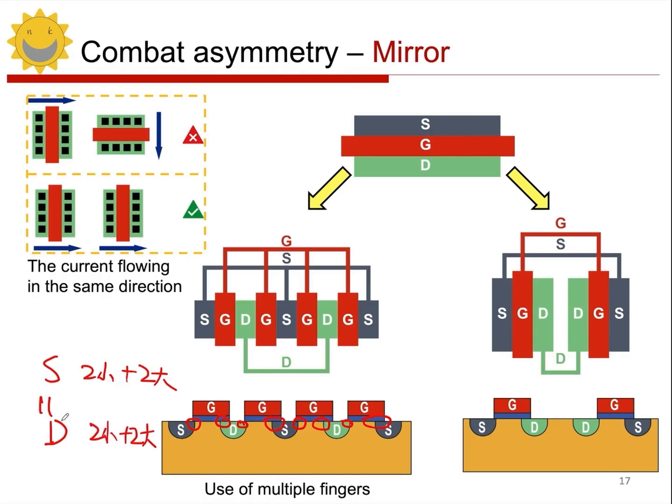Because of this, the overlap of each gate is different, so by drawing it this way, we can make the overlaps more consistent. This issue can be resolved through the use of fingers. Well, there are actually some issues with this. What I mean is, our original path area has something else, right? The parasitic effects of the PN junction, right? Because we are breaking this down, since we have 4 gates, the number of original paths that come out will be different. So the parasitic effects of the PN junction will also show some deviation. Because of this problem, there will still be some inconsistencies in the original path.